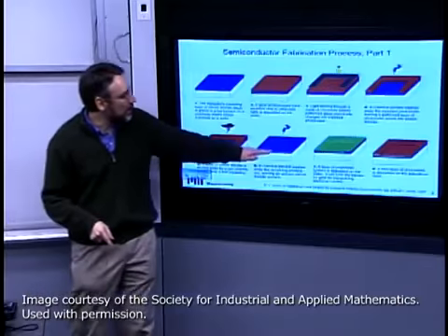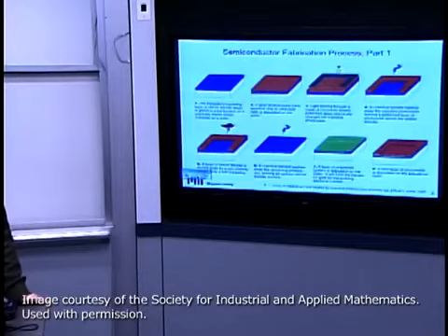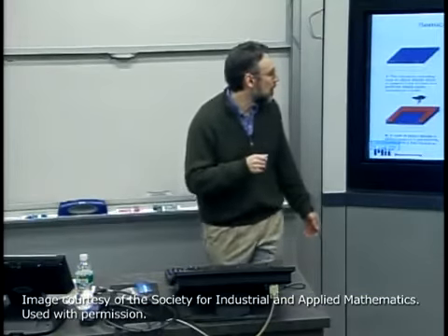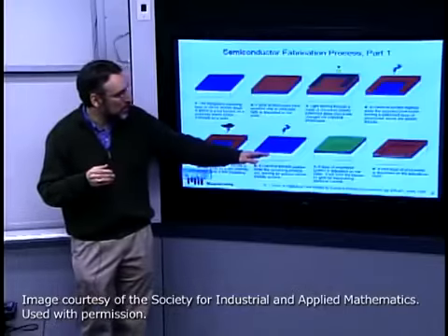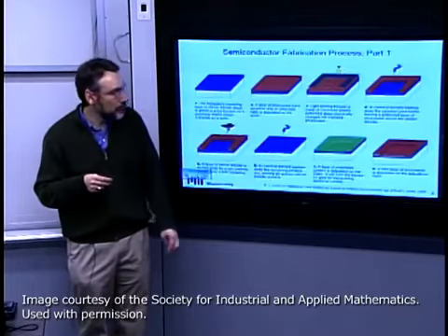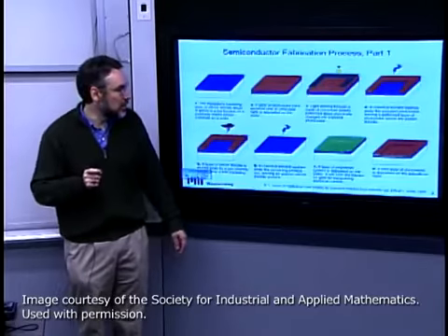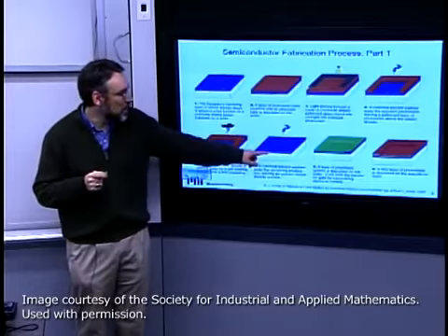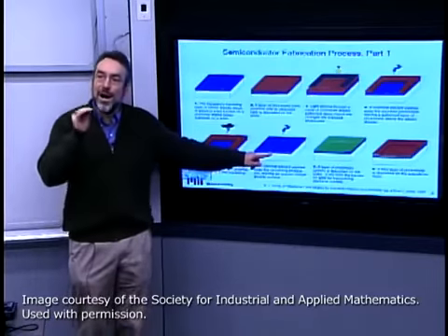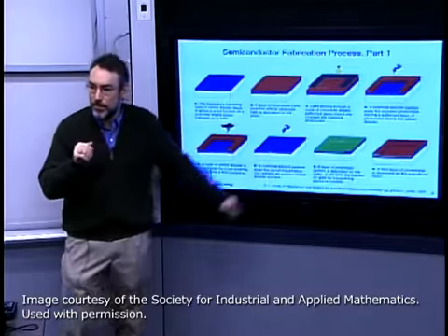Then I can go back in, and with different process conditions, lower temperatures, more pure chemicals, or even using alternative process technologies that involve very, very short time oxidations, rapid thermal oxidations, I can now controllably grow 1,000 angstroms or 100 angstroms or whatever I need. Okay, so that's the first mistake.